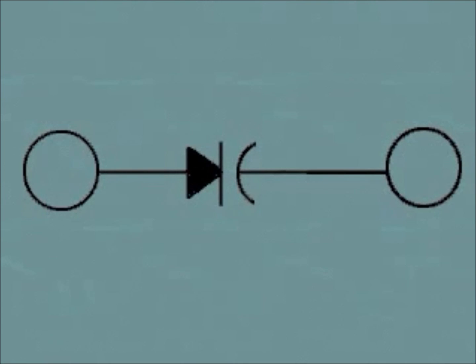The varactor tuning ratio is also called the capacitance ratio. It is the ratio of the diode capacitance at a minimum reverse voltage to the diode capacitance at a maximum reverse voltage. An important application of varactors is in tuning circuits. Varactors are used in TV tuners and other commercial receivers. The use of a varactor instead of or in addition to a capacitor in a tuned circuit gives rise to a voltage tunable resonant circuit. Such a circuit can be used in the generation of frequency modulated or FM signals.